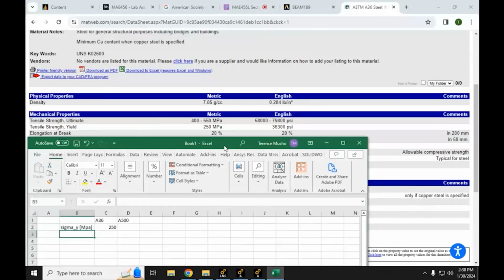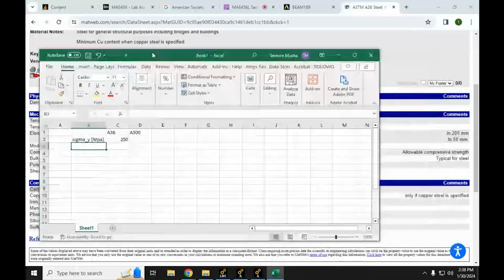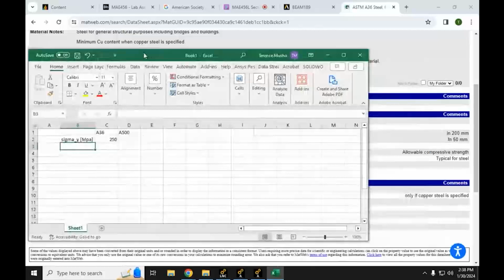Somebody can come and inspect the bridge and see if a crack has started. If you have a very brittle material, yeah, it'll have a higher yield stress. But often when you get cracks in these materials, they'll shoot through the material, catastrophic failures. Typically, for most materials that are dealing with potentials to overload, you want to have some ductility in them.